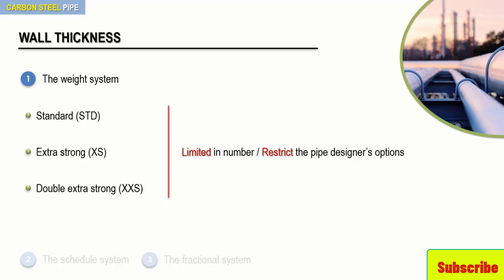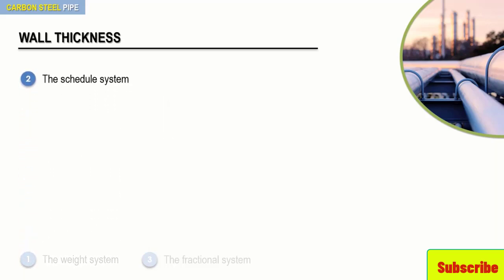With the development of new chemical processes, the methods of manufacturing pipe have expanded to meet process requirements. Such a wide array of chemicals and fluids, with their ever-changing corrosive properties and their extreme range of temperature and pressure variations, has necessitated the manufacture of pipe in additional wall thicknesses. Now called schedules, these additional wall thicknesses allow a designer to specify a particular pipe that will meet the exact requirements needed for quality installation and safe operation.